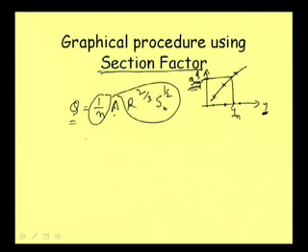So, this we can write as, out of this actually, 1 by n A R to the power 2 by 3. Now, for a given section, this component S_b to the power half, I am writing here separately, is called the conveyance of the section.